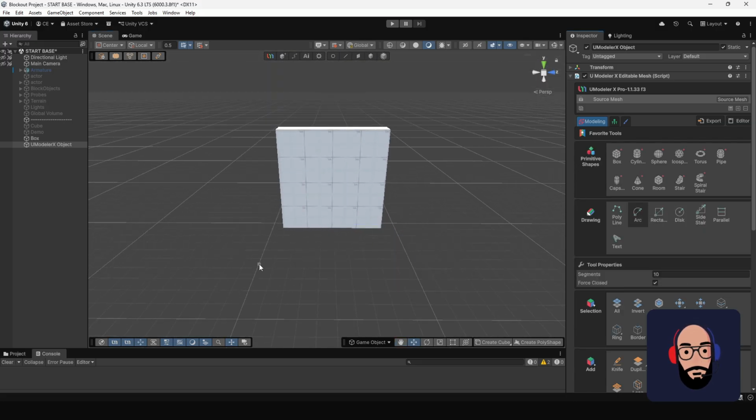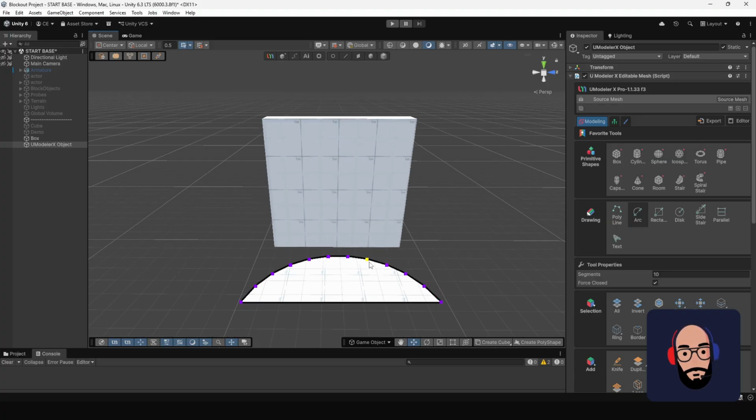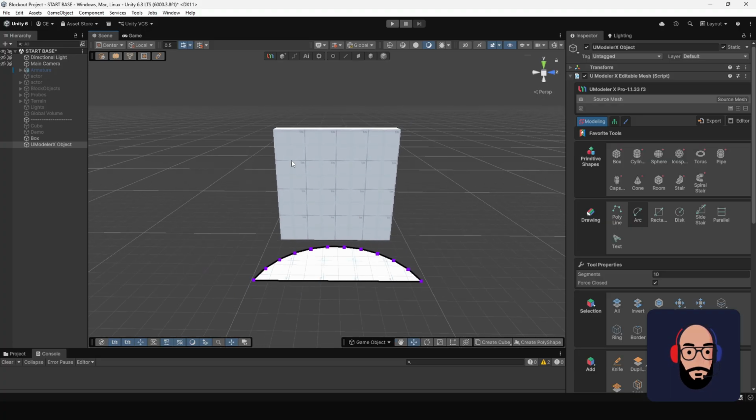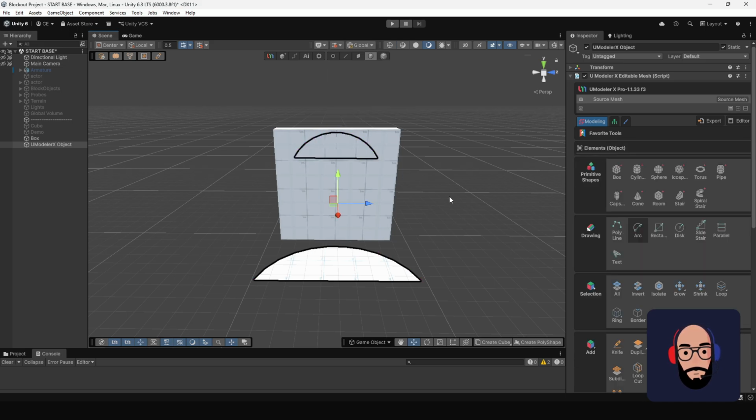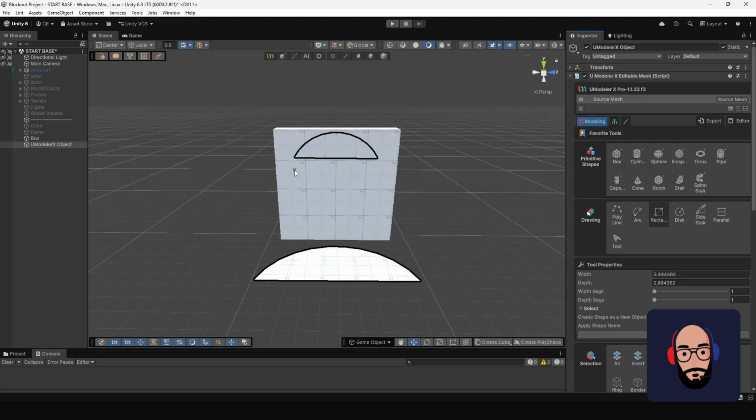When you click and drag in a scene, it creates 2 points. After releasing the mouse, move your cursor to define the arc and then click again to confirm. You can also draw arcs directly on a mesh, and then the new geometry becomes part of it. The rectangular tool works the same way. Just click and drag to create a regular rectangular shape.